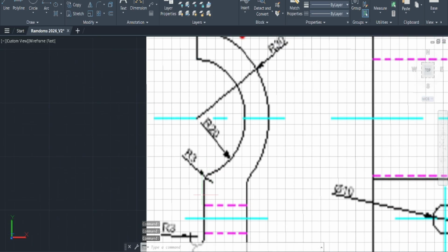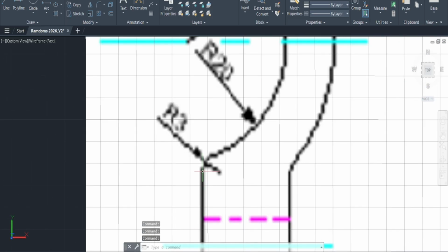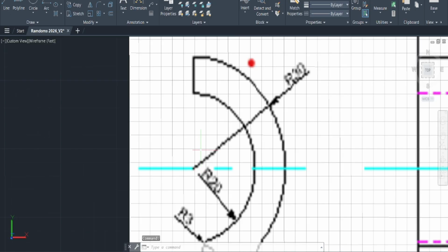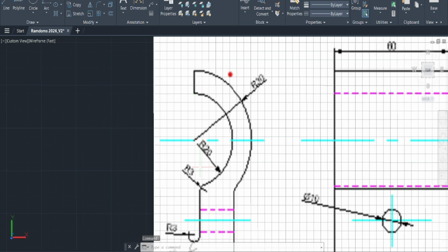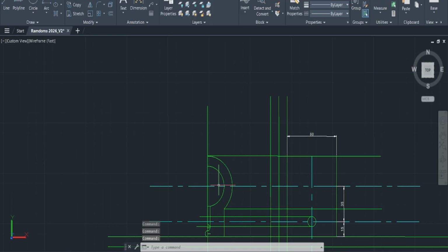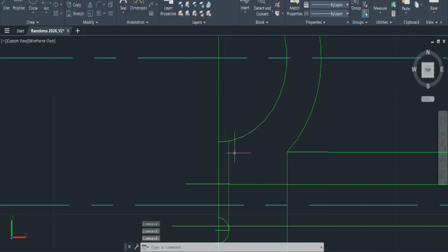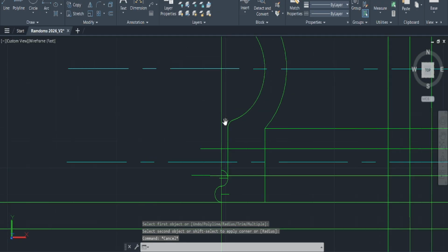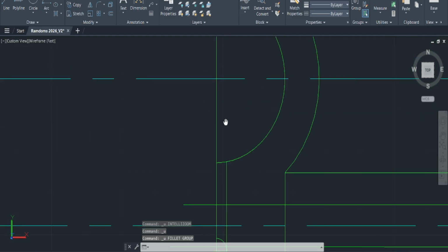We're gonna go up, so we can see there's an offset, and I'm just using the grid. We can see that hey, there's a small space here, but when we go up here on that same block, it's a little bit off. So yes, we have to go in. Awesome. So we know we're on the right track, and we would have done at least 2 of the shifts. So at this point, if you're using AutoCAD and you wanna conserve time, you can most likely just do your fillet, set your radius to 3, and then you could just click, and then you have that sweet fillet. If not, I'm gonna just delete it right now.